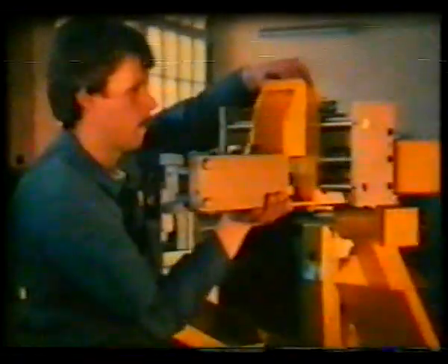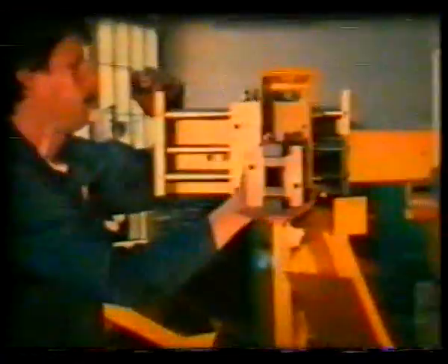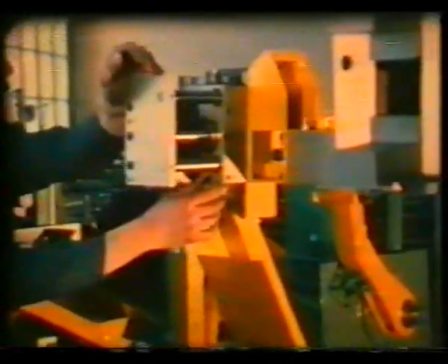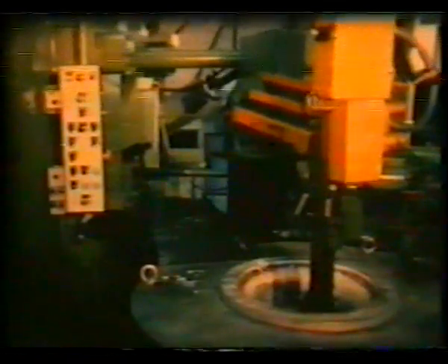For the automation of the die casting process, Buhler offers the Filmat and Picmat handling units. The Filmat metal dosing device ensures that an accurately proportioned quantity of molten metal is fed to the die casting machine.